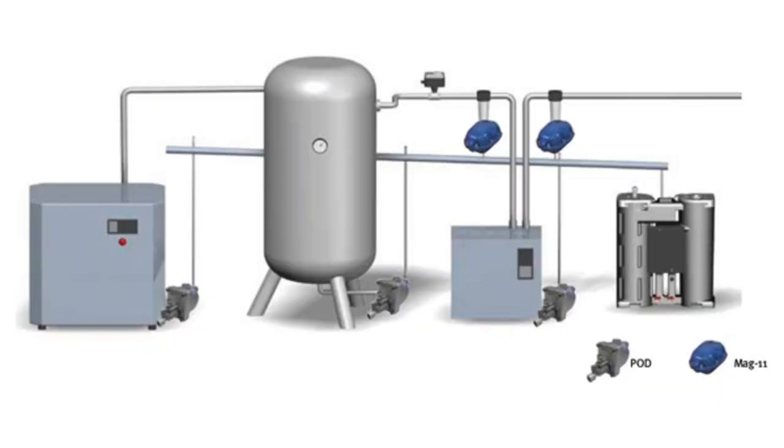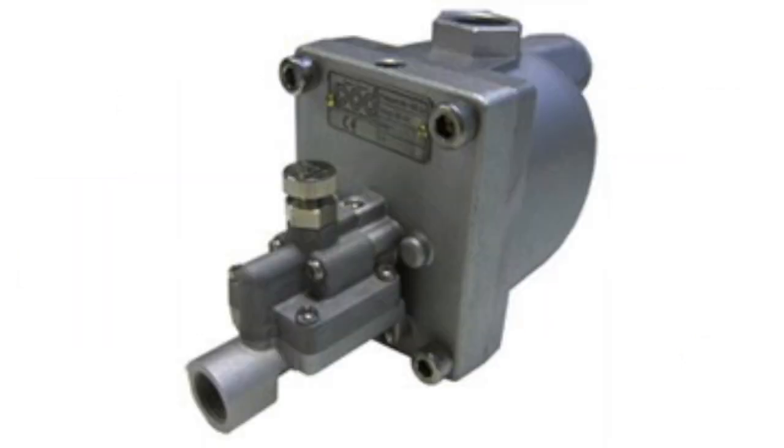This brings us to the idea of a smart draining valve. Here you can see a device on the bottom of a surge tank that monitors the tank's pressure. When the pressure passes a certain programmed threshold, indicating that there is too much water in the tank, the smart device will open the drain valve and empty the water out. When the pressure gets low enough, the drain valve will close.